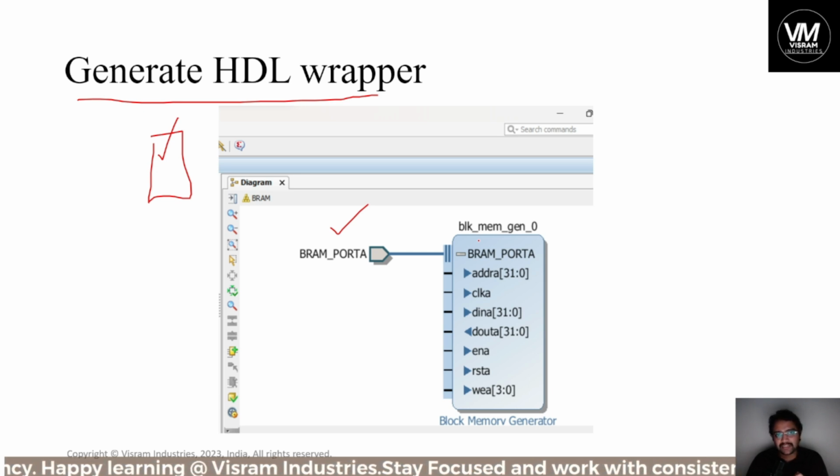In that packaging you will also find a user guide manual that can be found online as well. In that user guide manual you can see what type of block RAMs you have in the FPGA. Every FPGA has these memory blocks, which are BRAMs, and for that BRAM there is a syntax of the Verilog HDL that you can write.